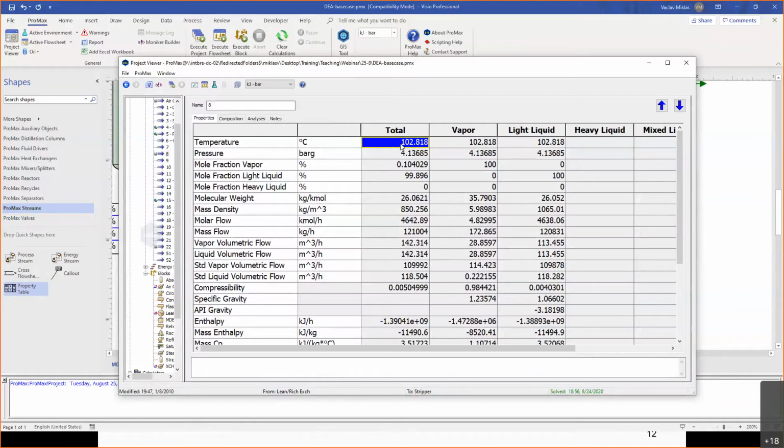And since heat duty is part of the heat transfer equation, it changes the area required and changes the fraction over design. And based on this, with a few steps that are all handled by ProMax, we are able to tune the fraction over design to be 0, and we are basically able to predict the real temperature coming out of the heat exchanger.